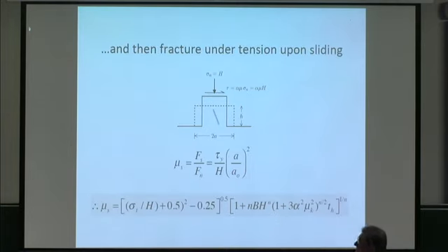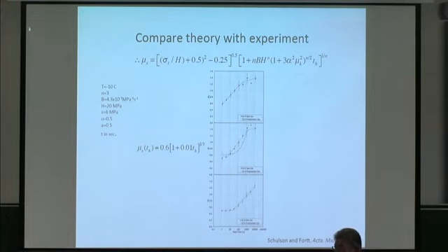But what's the result? The idea is that once sliding is re-imparted or imposed, then eventually the contacts must come apart. The failure, the coming apart, I believe, is a tensile fracture. For the sliding induces a tensile stress within the asperities, and the principal stresses are such that the principal stress will be lying at some angle less than 45 degrees. Fracture occurs of that kind, we think. If we then put into the criterion simply the tensile strength of ice, one ends up with an expression of the kind you see here, and what you really want to know is, is it any good?